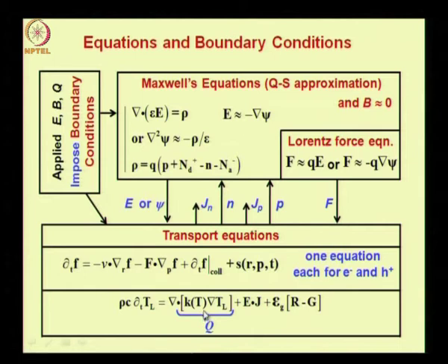which is written as proportional to the temperature gradient of TL. The constant of proportionality is thermal conductivity, which is a function of temperature, and that is why this K has not been moved out of the divergence sign, because it is a function of temperature, and temperature can vary with x, plus source or sink terms.